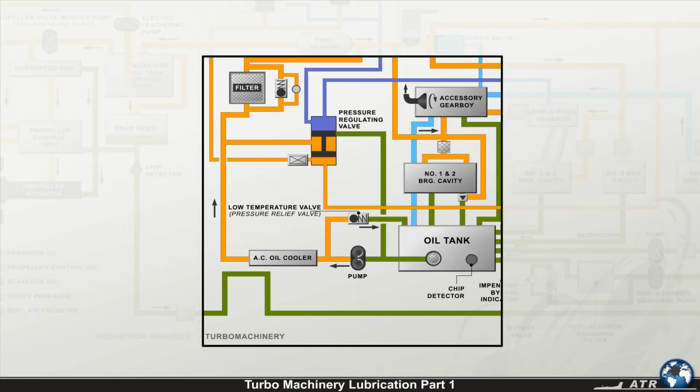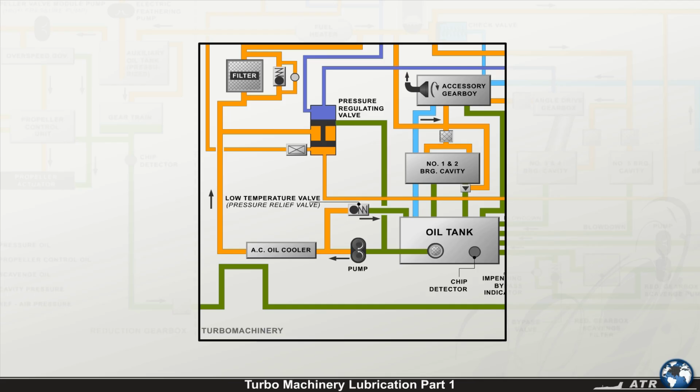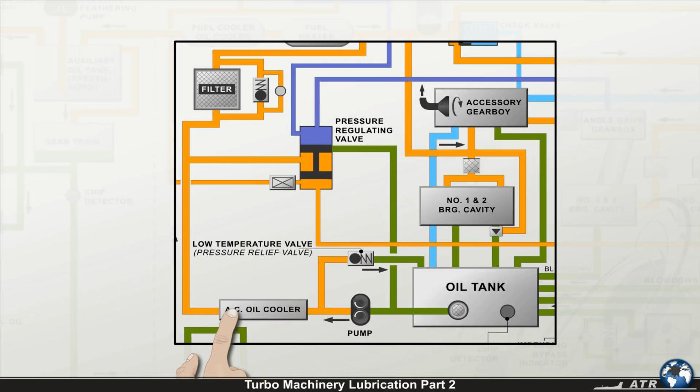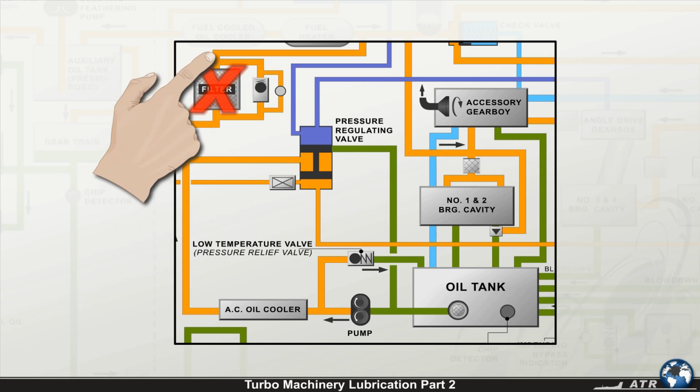As soon as the starter generator initiates the engine start sequence, the oil gear pump will be driven via spur gears and sucks oil from the engine oil tank. The low temperature valve is installed after the oil gear pump to return oil to the tank in the event a pressure surge is sensed during cold starting. The air oil cooler bypasses the oil until above normal operating temperatures are achieved. Oil from the oil gear pump flows through the high-pressure oil filter. In case of a filter blockage, the oil will be bypassed through the filter bypass valve.